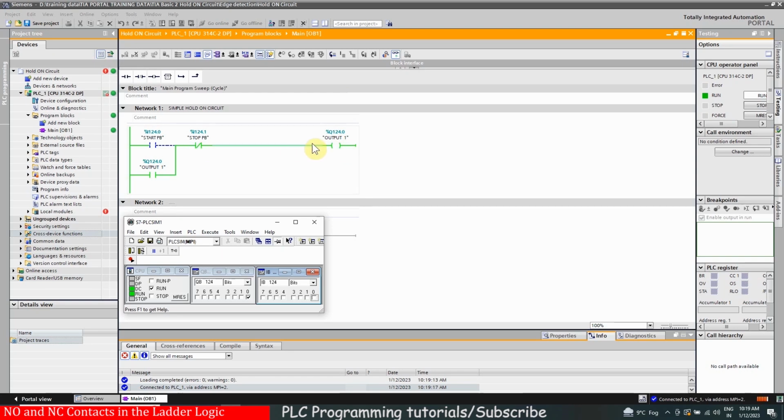Now to turn off this one, we have to trigger this input I124.1 by pressing the stop push button once. What it will do is open up this NC contact. So once this normal close contact is opened, it will break the logic path from here and turn off our output Q124.0.